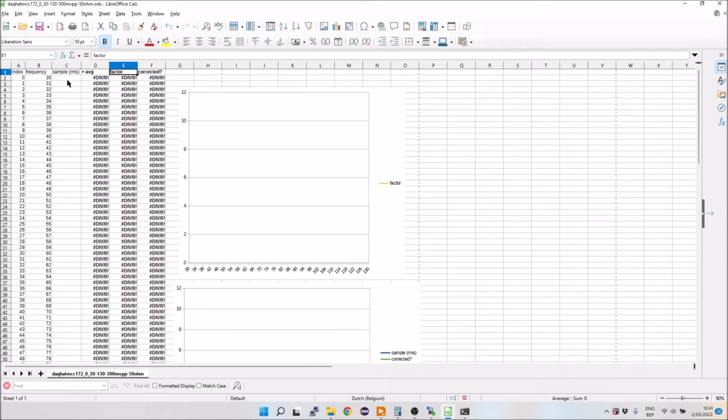I will then put those values, the correction factors, into another spreadsheet, and that will be used as the input in my final execution. LabVIEW will read this spreadsheet, and at every frequency it will apply the correction factor that we calculated here. And if everything is fine and the stars align, I would get a linear output from the piezo sensor when doing that second run.